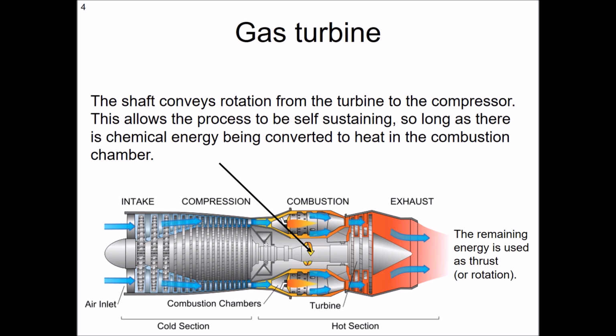So of course this differs from a reciprocating engine. These are discrete phases. They're not all in the same part, are they? The compression's done in a different part of the engine to the combustion. So that's different to a reciprocating engine. Okay, so we've got very hot gases now, and what we can do is we can expand these gases out the back of the engine. That's what we do. We expand them out the back of the engine, and then they go into the turbine section. So you should be able to see that there's what looks like 3 turbine stages in this particular engine.